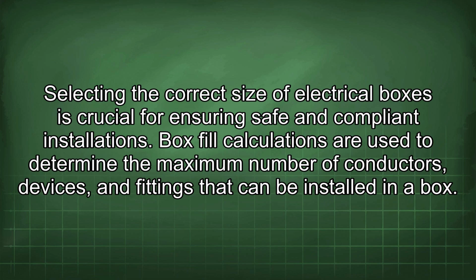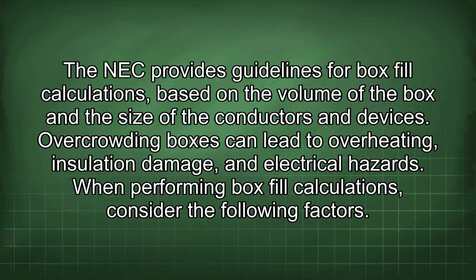Box fill calculations are used to determine the maximum number of conductors, devices, and fittings that can be installed in a box. The NEC provides guidelines for box fill calculations based on the volume of the box and the size of the conductors and devices. Overcrowding boxes can lead to overheating, insulation damage, and electrical hazards.